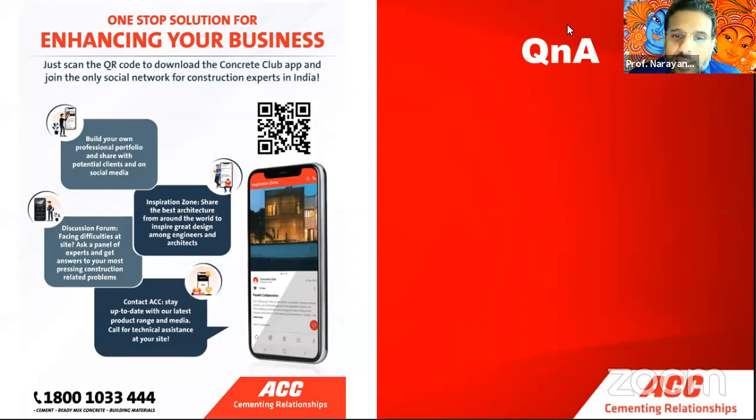How can high strength concrete help small buildings and individual residential buildings? No, if you're using it for 3-story buildings, you're wasting a lot of money. Don't even bother. If you're not doing more than 10, 15, 20 stories, don't even go near it, because you're just spending money. What admixture may be used to reduce cohesiveness, stickiness of UHPC?